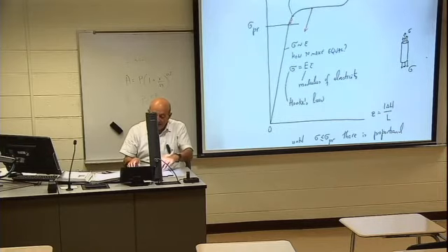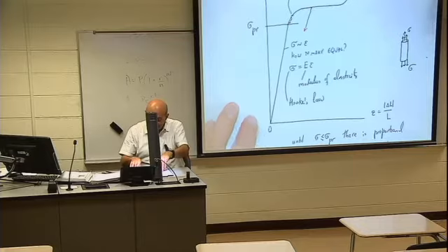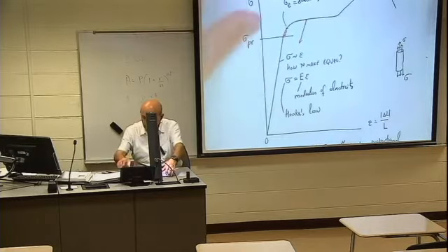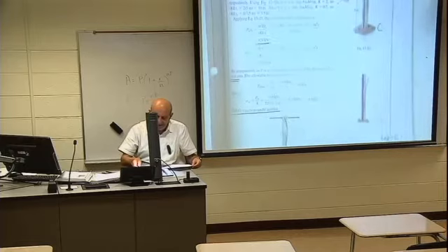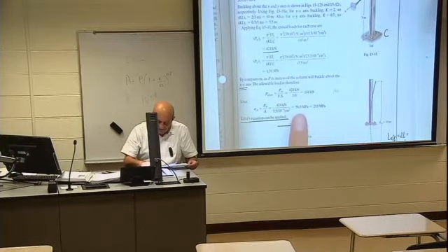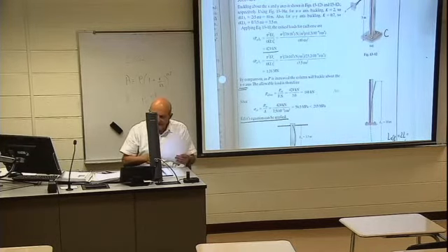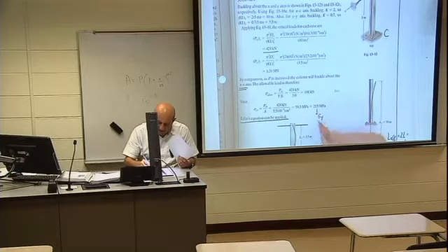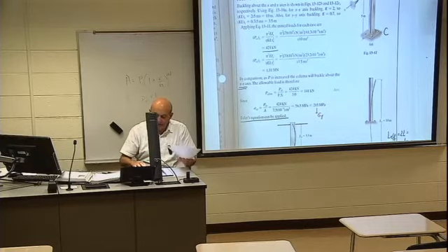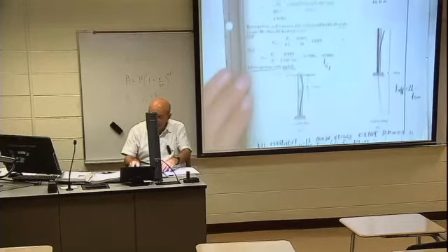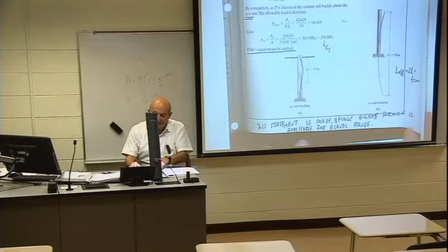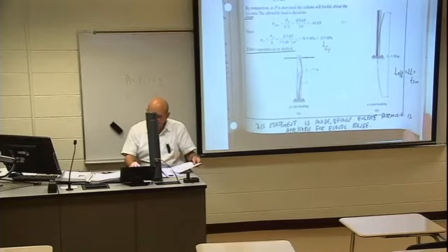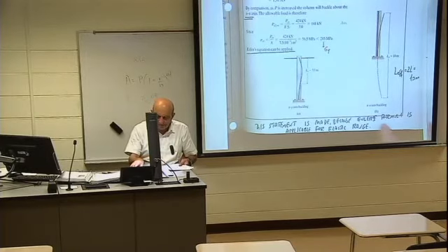But in this particular problem, we said that this value that we obtained is less than this value, which is sigma yield. And therefore, Euler's formula can be applied, because for obtaining Euler's formula, we used elastic behavior. So I will continue. Any questions?